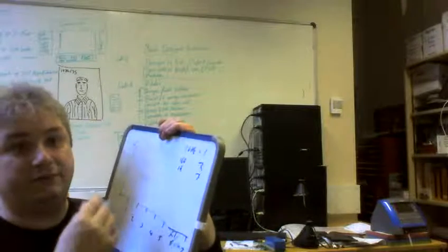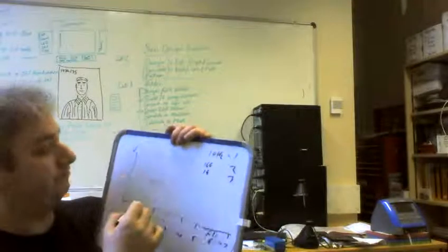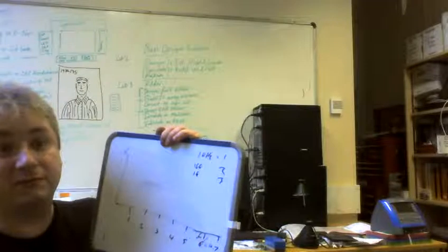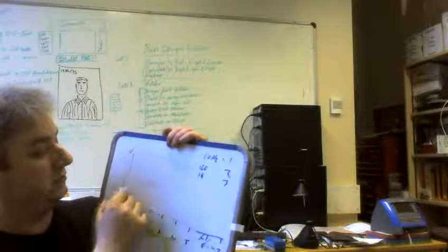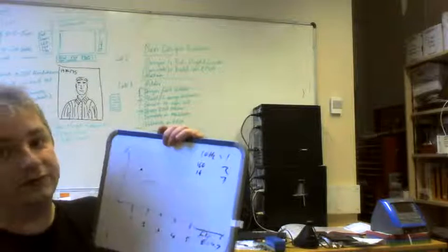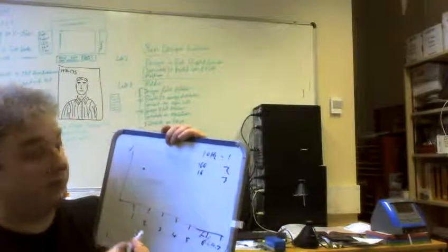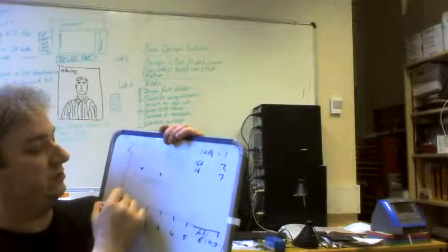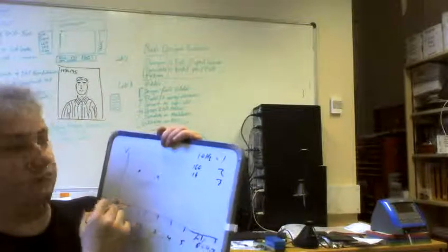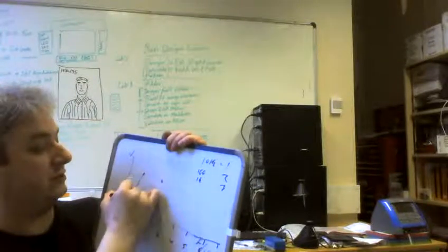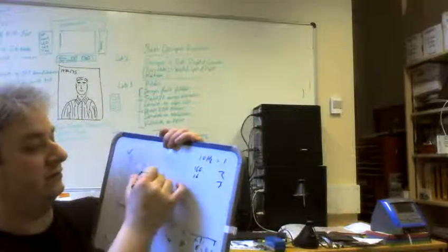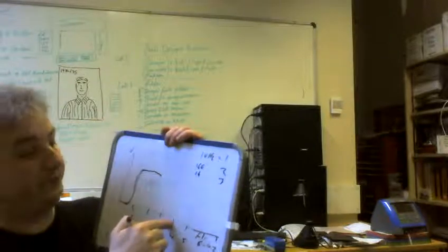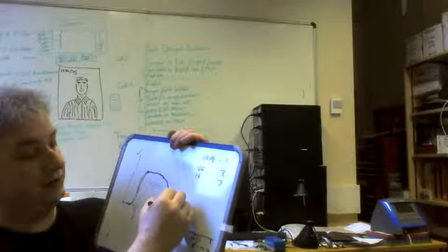With the multimeter, it actually works from roughly around 10 hertz. So it's working perfectly fine around 10 hertz. Let's put a dot there, up to kilohertz, which is 3 here. It didn't work at all well below 10. Up here around 10 kilohertz, 4, it's getting half, so it really did tail off.